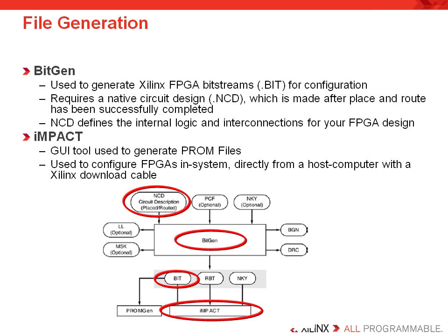First of all, BitGen is used to make your bitstream. Of course, this can only be completed after the design has finished implementation, which means that a finished design has been made by the implementation tools and a correct NCD file is available and has been completed. As you will see, the NCD file contains everything about your finished design. That means it is a required input to the FPGA Editor, which is one of the utilities in the ISE tools, and is used to understand the design in gross detail.